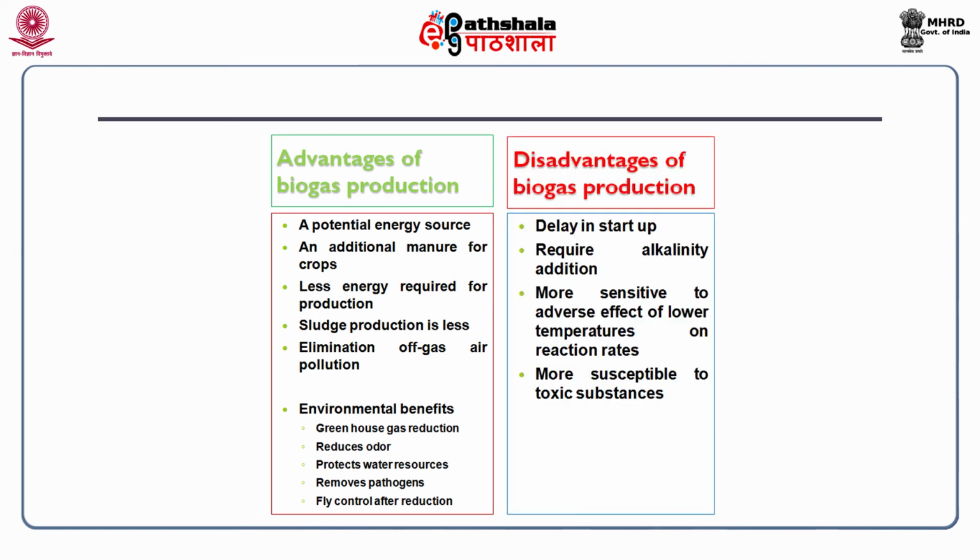But the disadvantages are the delay in the startup, it requires alkalinity addition, it is more sensitive to the adverse effect of lower temperature on the reaction rate, and it is more susceptible to toxic substances.